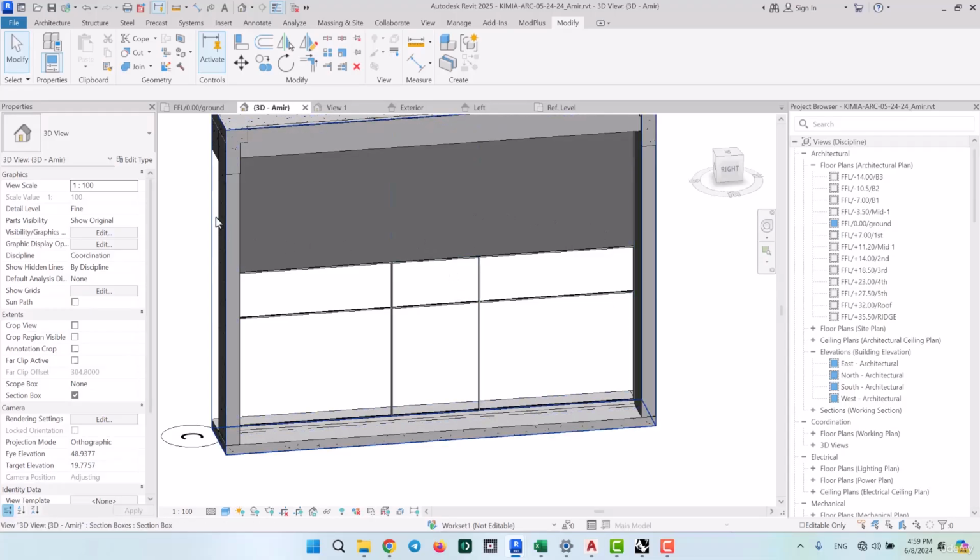Or if just like now they tell you that you need to place a solid panel, you should know that you'll need to remove the extra mullions and grids, create a new solid panel family based on the dimensions and requirements, and then place it where it needs to be. Something we're going to be practicing a lot throughout this course is how to perform and apply such details on your projects. It doesn't really matter what kinds of details this project has.